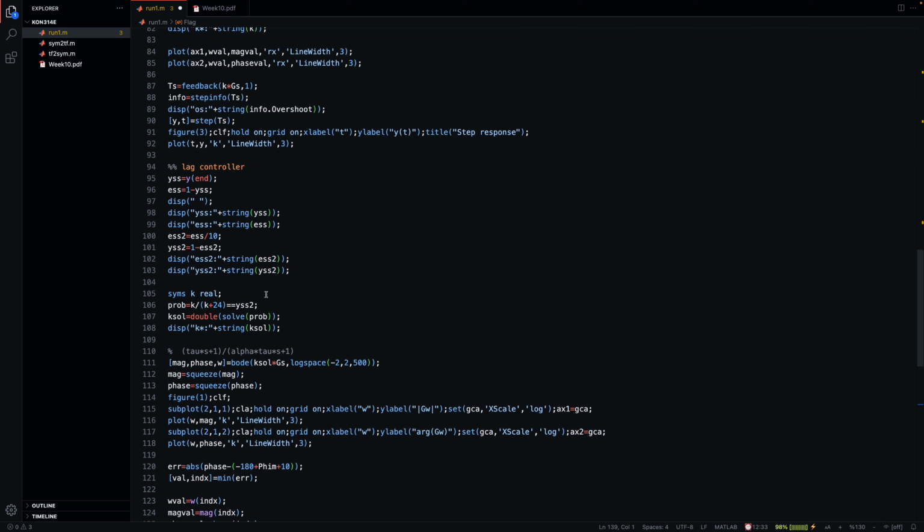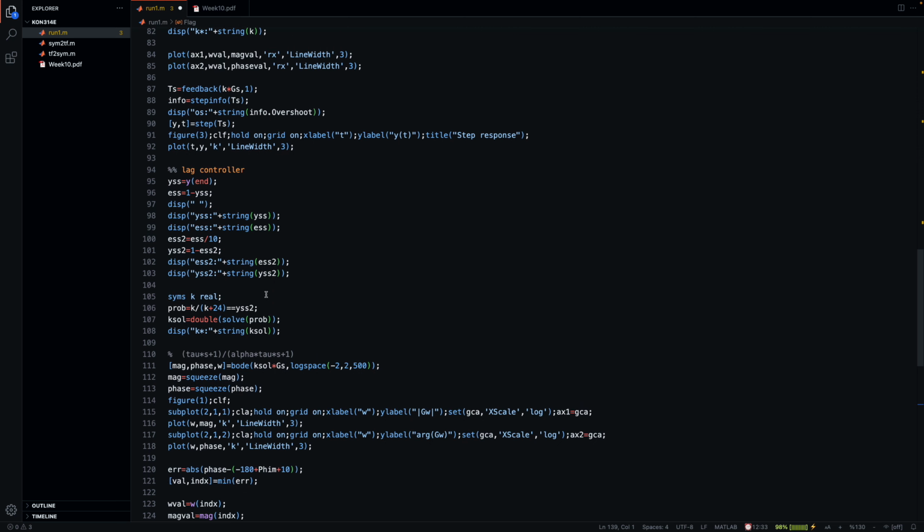Now, as it was the case for the p-type controller, no matter if it's the stability or if it's a synthesis problem, the steps are quite clear. And you have to just obey the rules, just follow the steps, and you are going to design a controller. That's a nice thing about the frequency domain methods, because they will be a step-by-step design method, kind of an algorithm, and you should follow the algorithm, and that's basically it.